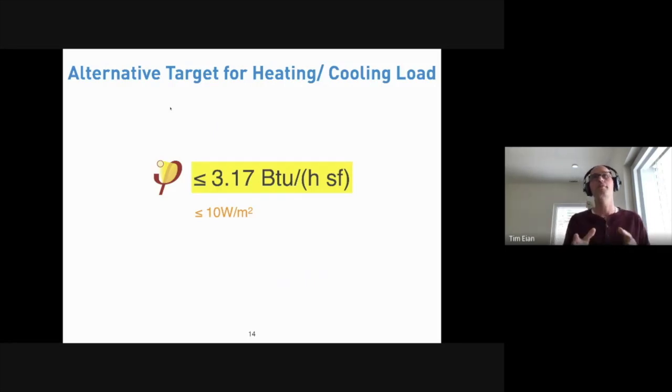But if you can design a building that lives within those means, the reason why that is something that they encourage people to do is you can actually supply the little bit of heating energy this particular building would need through the ventilation system alone, and forego any freestanding or additional heating system for the building in its entirety. And in some parts of the world that works handsomely. It doesn't work in Minneapolis and Minnesota because our temperature swings are just too great for that, especially on the cold side.